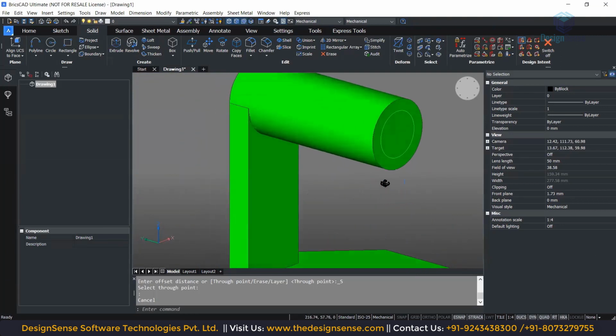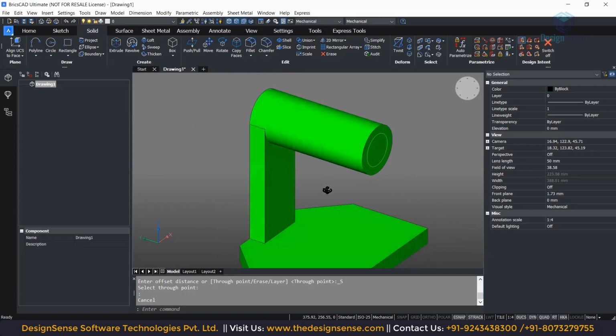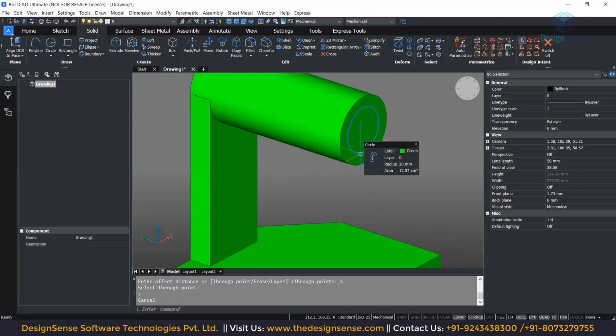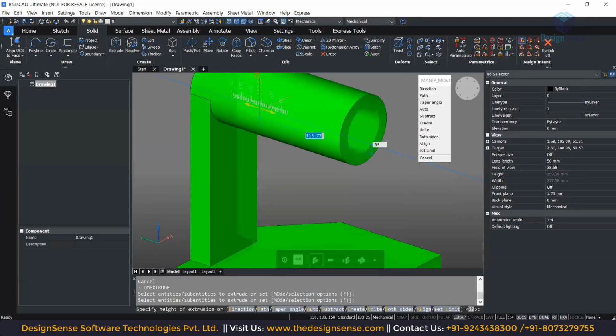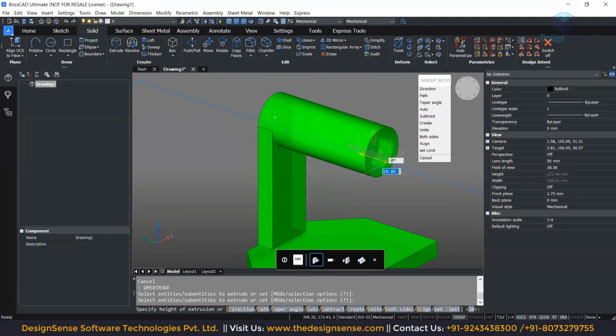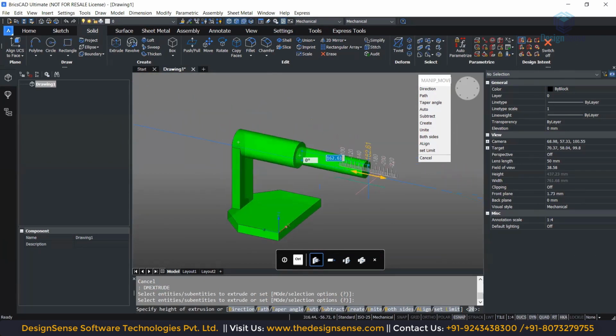Now, this particular offset, I want to completely cut extrude through the entire cylindrical profile that's there. So for that, I'll simply hover my cursor onto this offsetted sketch that I just created. Again, you can simply use the extrude command, or type in DM extrude as well, to be able to cut the circular profile from within the solid. I'll select the sketch, and once you do that, you can simply move outwards. BricsCAD again is smart enough to understand that if I'm moving outwards, if there are no intersecting solids, it would create a new profile.